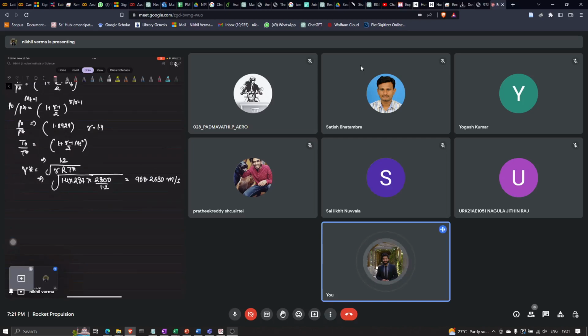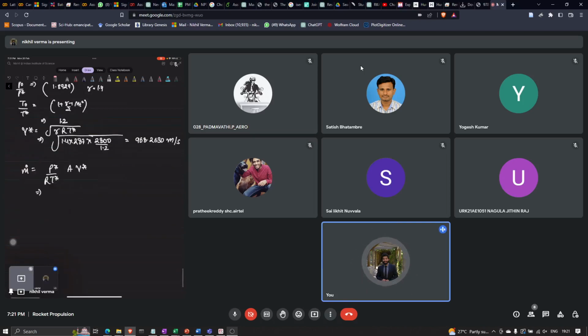So m dot at the throat is rho star, P star by R T star, into A into V star. We can multiply and divide by P naught, right? So you will get P naught by T naught, and also we can multiply P star by P naught and T naught by T star.